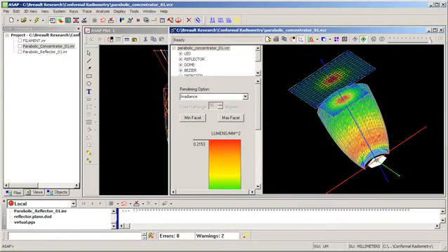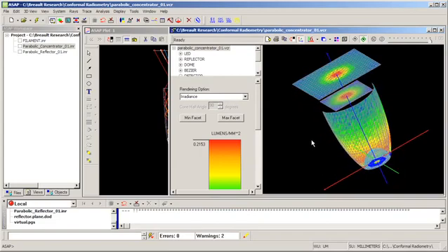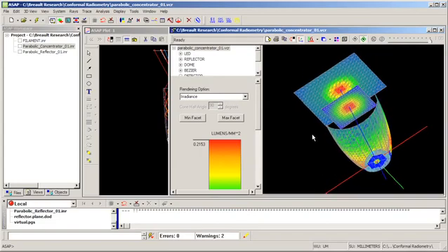So we've now mapped the radiometric information that we calculated for this example into our 3D viewer. And we can see that one thing we didn't mention was that we added the bin keyword modifier, in this case, to virtually every surface in the system. And so that information has been plotted for all the surfaces that we see. Now we mentioned earlier that we added two detector surfaces, which in this case were defined to be transparent and therefore have no effect on the resulting ray trace. And yet we see that we have correctly calculated the irradiance at each of these two surfaces.